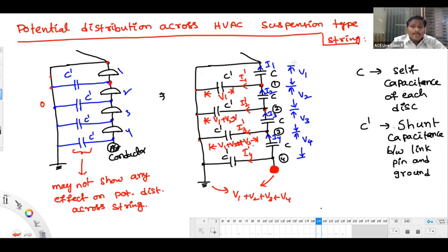Yeah, so I'm explaining again. Please listen. Why are voltages V1, V2, V3, V4 becoming unequal? The reason is I1, I2, I3, I4 are becoming unequal. Next, why are I3, I4 becoming unequal? Because of I3 dash current. If I3 dash is 0, I3, I4 will be equal. Why are I2 and I3 becoming unequal? Because of I2 dash.